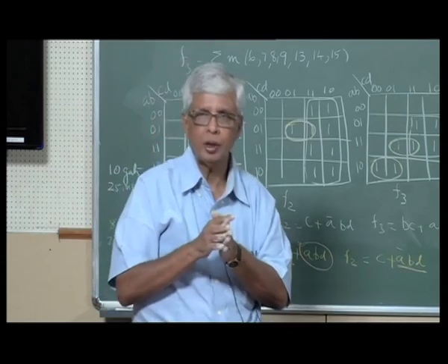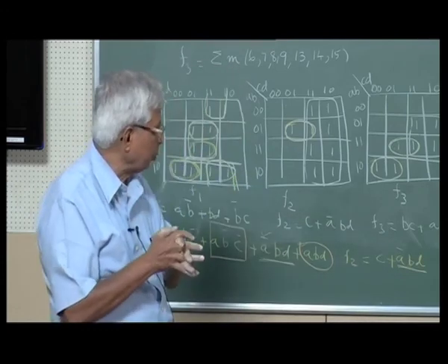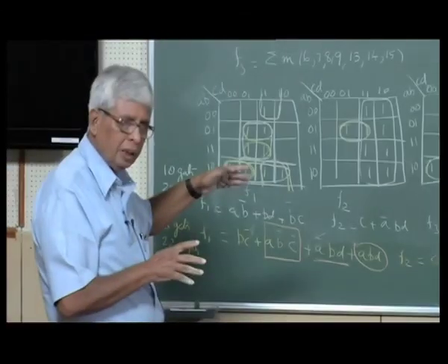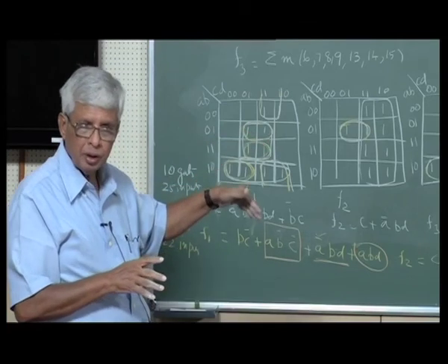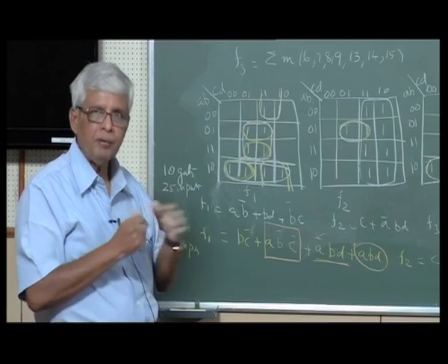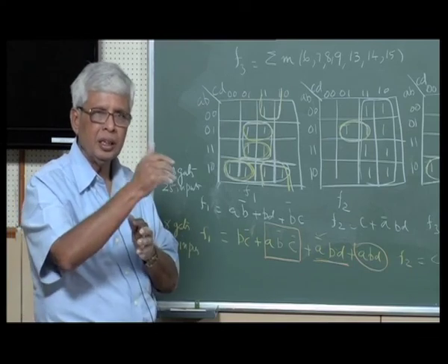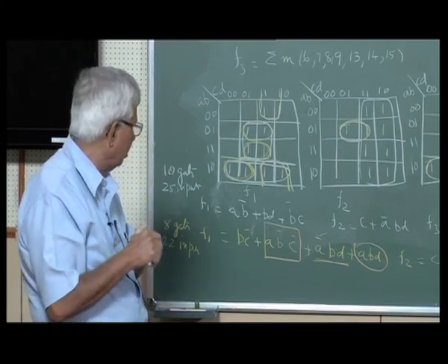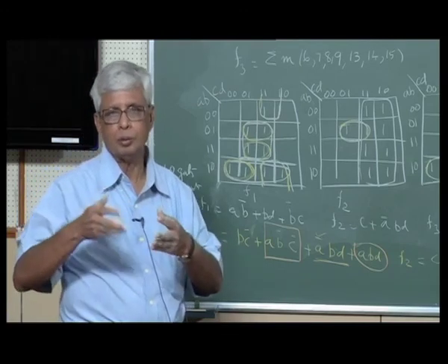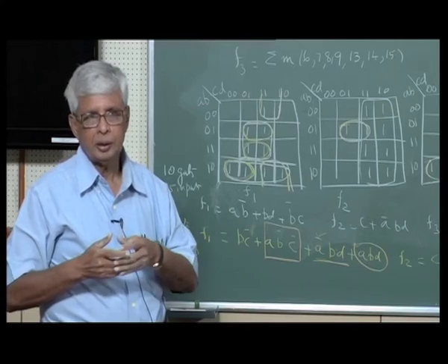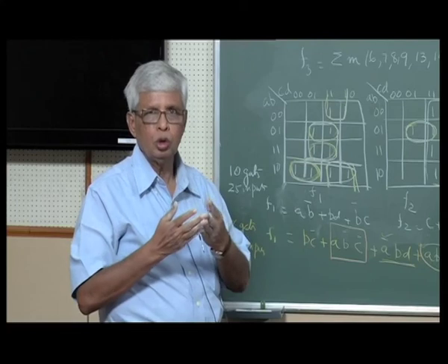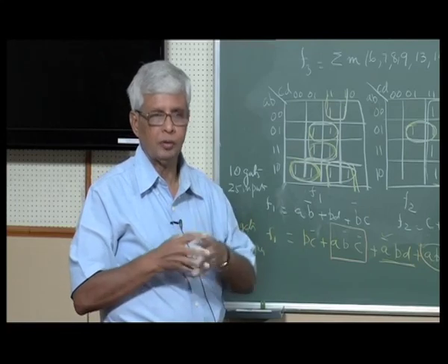The first of the programmable logic devices we saw was ROM, where we have a series of inputs producing all the possible minterms, combined in different OR gates to get the outputs. The problem is we have too many minterms, many of them used only once or twice, especially when a large number of inputs and outputs are there. The size will be huge, but I may be using only a small part of it.